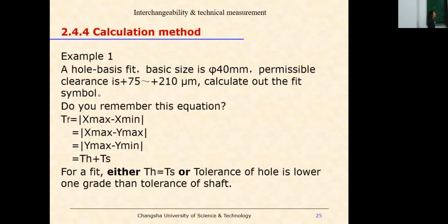Yeah. So the shaft is also IT 9, right? Yeah, because this is larger than 8, right? So we choose IT 9 for the shaft and the hole.